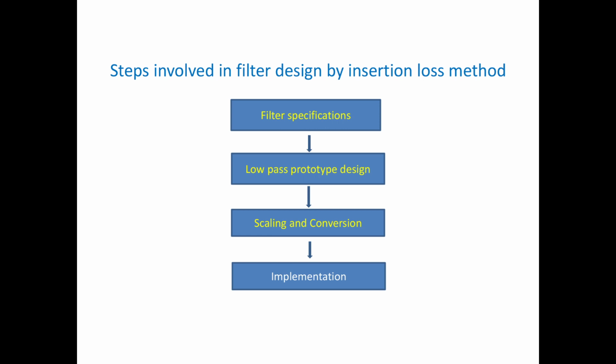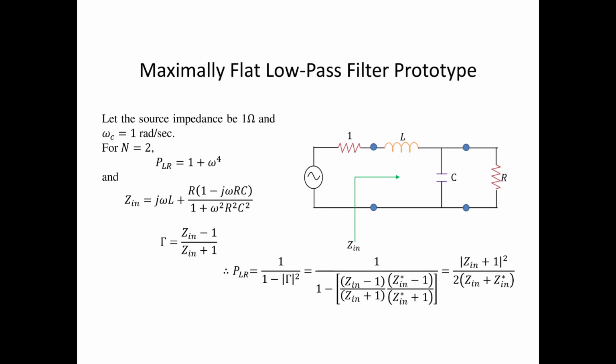Design steps in filter design by the insertion loss method. First you have to mention the filter specification, then low pass prototype design, scaling and conversion, and implementation.